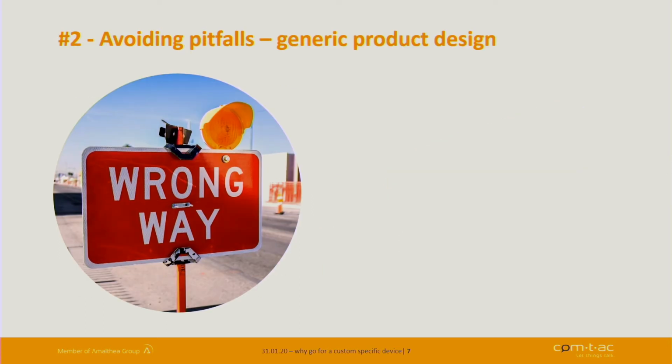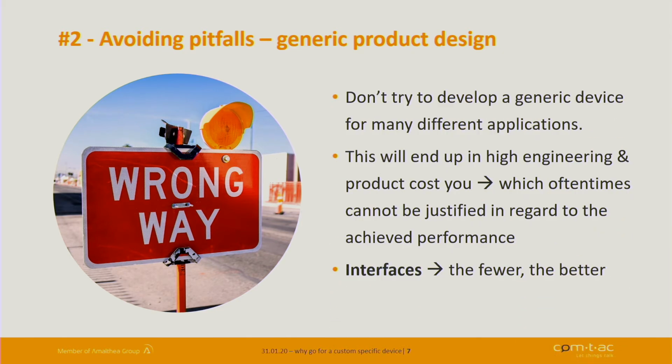The second one is, we often see that a lot of people, when they start to think about a custom-specific product, like to insert as many interfaces and as many sensors as they can think of, thinking we are ready for all types of applications. That's true, a simple temperature sensor doesn't cost that much, but you need payload size, you need extra battery, and you need firmware that supports it. If you take all those things, you have a generic device which is not fit for an exact use case. So we recommend, think about every sensor you'd like to use in your device and question whether it's really needed. Otherwise, it's better to have different devices.